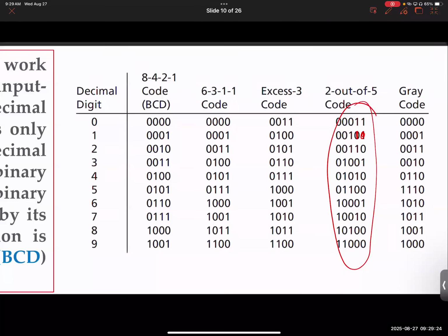It is self-checking. And we use a parity circuit to check whether there are 2 ones. If instead of 2 ones there is 1 or just 3, then we know there is an error. So you correct that portion somehow, or discard that portion. If there is no error correction available, just disregard that portion, that it's invalid. And it happens all the time, by the way, not just for radiation strike. There are many other reasons why mistakes can happen.